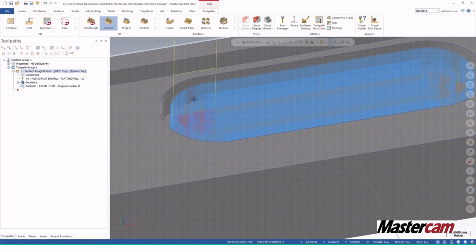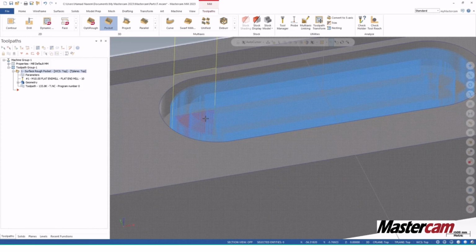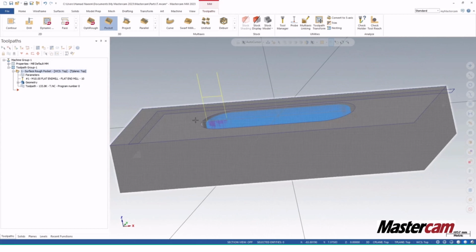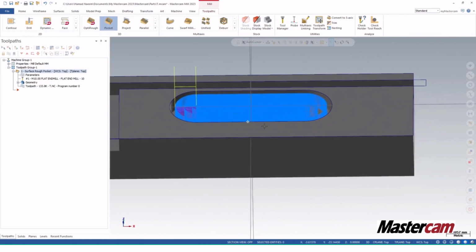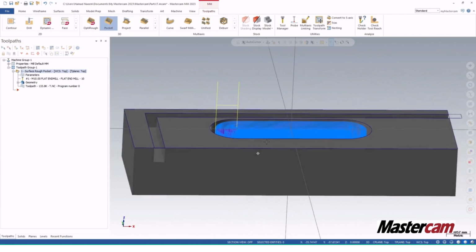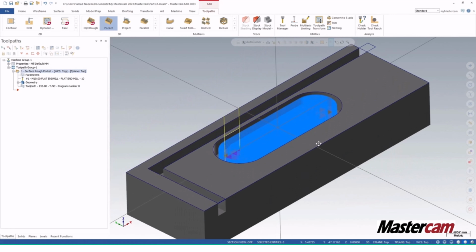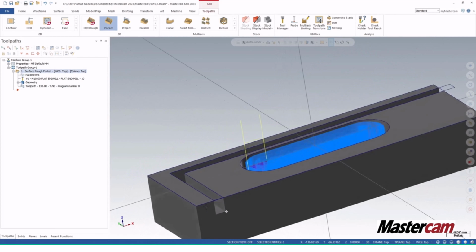So we take a 0.5 millimeter depth cut, and it goes down from the top of the stock, from top to bottom, minus 15 millimeter, and creates this pocket. So this is how we can create 3D toolpaths. It just gives you an idea how we are going to perform 3D toolpaths for our 3D models. Okay, so now let's do another